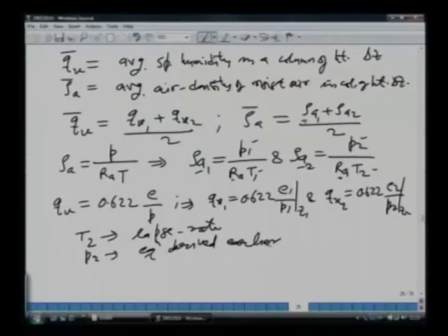Okay. And also this E1 and E2, we use dew point temperature at those heights, and if we need to calculate E, the saturation vapor pressure, we can use the temperature in degree centigrade. Okay. So, you see that we have a small little expression with which we should be able to find out the amount of precipitable water in a static atmospheric column. It is a useful exercise.